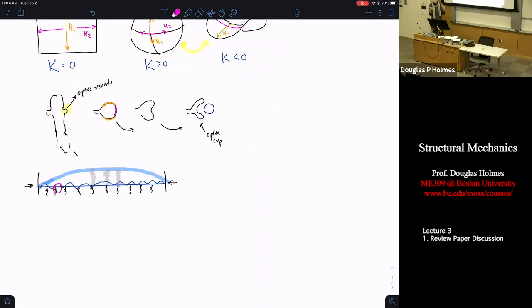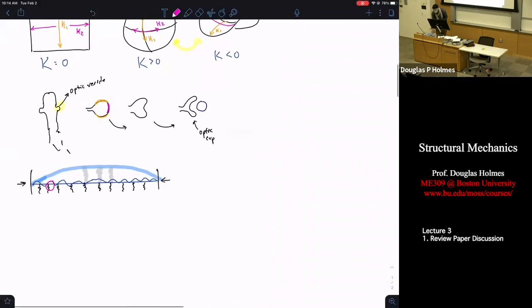So what happens is your wrinkles adopt some sort of balance in between the two. It says, all right, I want to bend into this big arch. You want me to bend into this tiny thing. Let's meet somewhere in the middle, and we'll find a wavelength that's somewhere in between those two things. And so what dictates that wavelength is a balance of how hard it is to bend the object relative to how hard it is to stretch the springs.